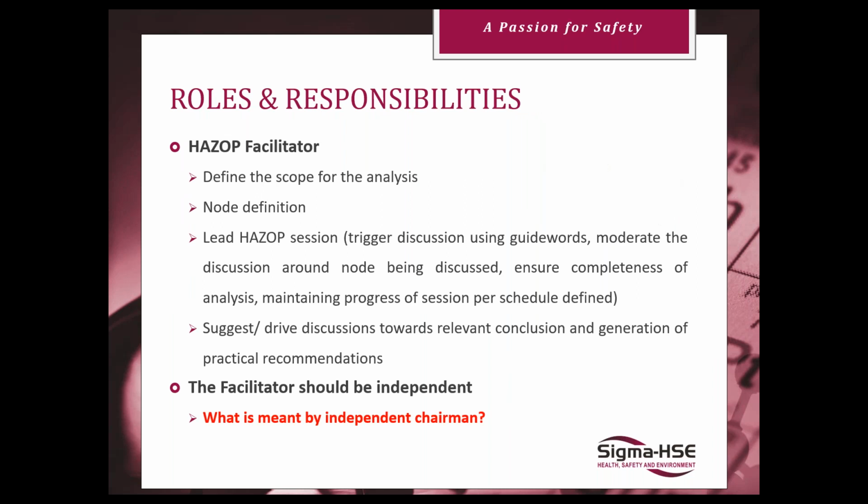All right. So roles and responsibilities. HAZOP facilitator, he'll define your scope that you're analyzing. Where does the process start? Where does it end? And within that scope, he'll go and he'll define your nodes. And he'll lead the session. He'll talk about what guide words we're using, what parameters. Direct the flow to kind of keep the meeting moving and to keep the conversation relevant. A lot of times you'll run into potential for people to try and solve design problems within the HAZOP session.